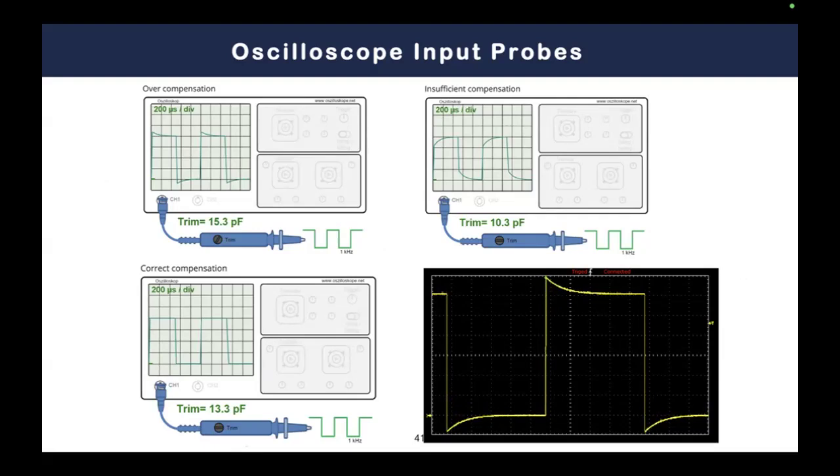And this single frequency might already pass even with the presence of a capacitance mismatching. But in order to check the capacitance matching and the calibration process of your oscilloscope, you have to go to a sharp edges signal, and the best one you can use here is a square wave, where you can test the capacitance matching of your oscilloscope.